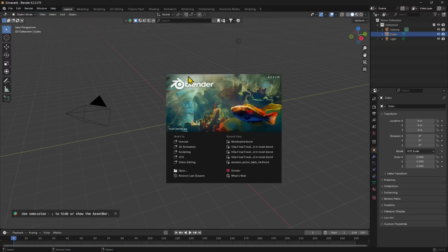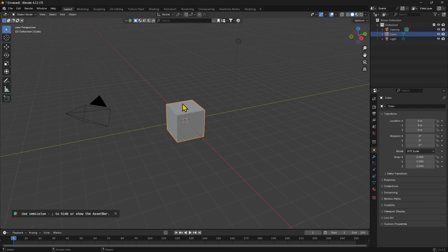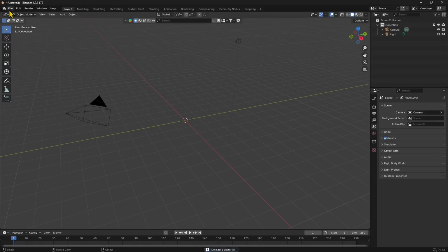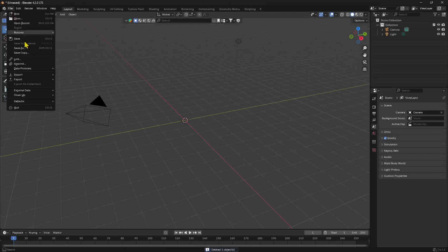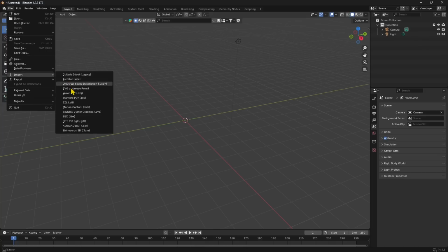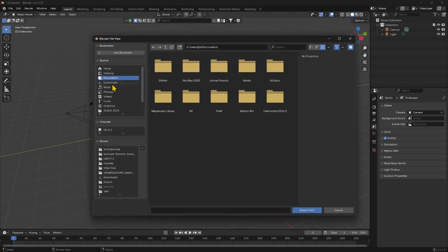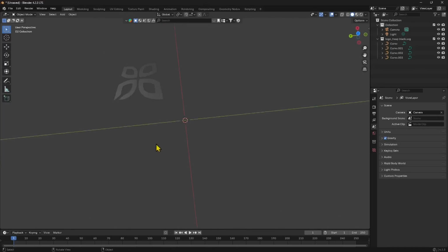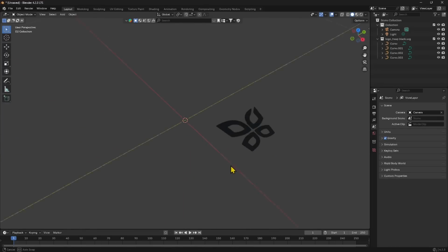I'm going to do an example in Blender just to show you also a little bit of 3D. So it's kind of an extra you may want to do or may not. Blender is free, it's open source, you can download it. And you can also check our video courses in Blender among the other courses. So I'm going to go to File, Import, and look for the SVG format in here. It's supposed to be there, and there it is. And then I'm going to select the file that I downloaded in my download folder, and there it is.